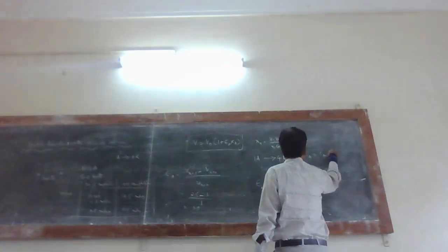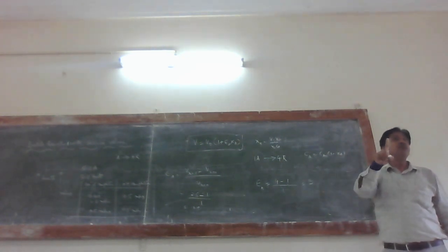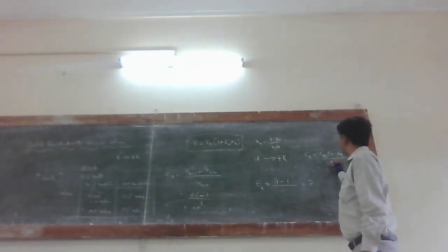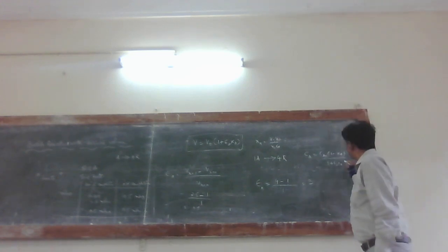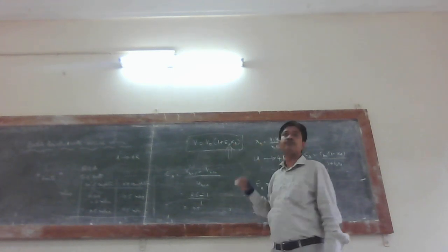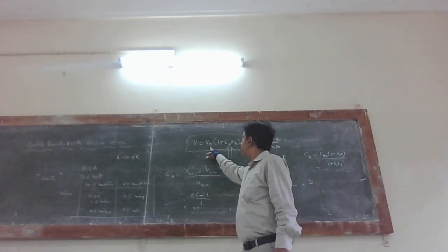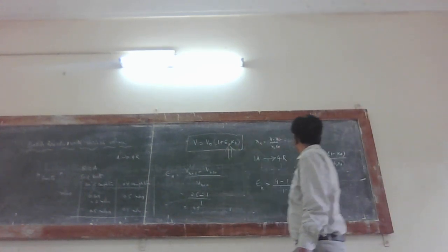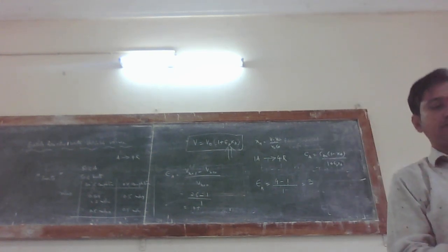See, already you know this formula: Ca is equal to Ca naught into 1 minus Xa, for the constant volume case. Whenever variable volume comes into the picture, just divide by 1 plus epsilon Xa. This term will come from all the equations, because this is the only term affecting the volume. Your volume is equal to the initial volume times this particular term. This will come into the picture every time in all the equations. So equation number 66. Clear?